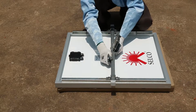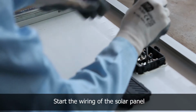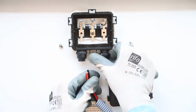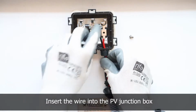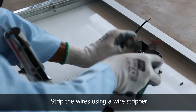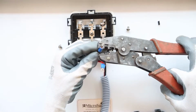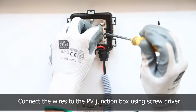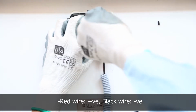After fixing the panel to the module mounting structure, start the wiring of the solar panel. Strip the wires using a wire stripper and connect the lugs using a wire crimper, and then connect it to the PV junction box. Red wire positive, black wire negative.